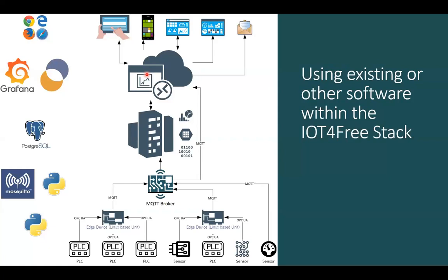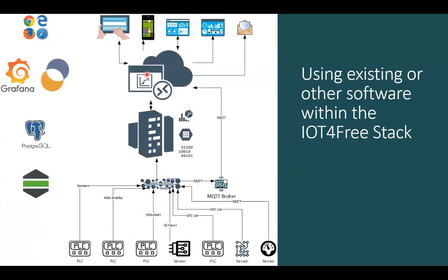You can substitute or augment the edge device with the PTC Kepware product. In fact, with the proper add-ons, Kepware can be used to replace the data capture, abstraction, acquisition, and ingestion layers. For that, specifically, you'd use KEPServerEX, probably the Manufacturing Suite, IoT Gateway, and Data Logger.